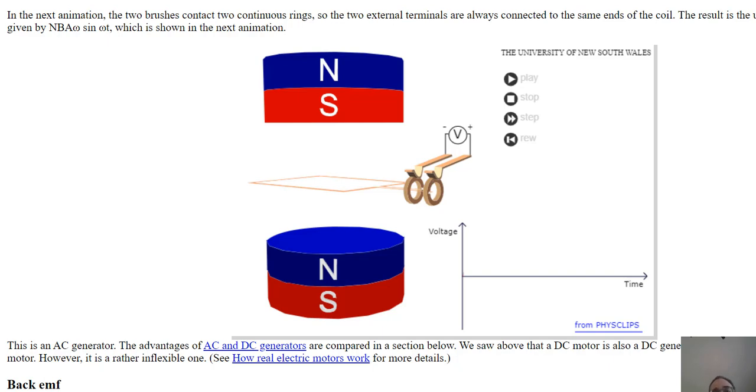Okay. Now, nuclear power, while it may sound really different, is actually almost identical. The only difference is what heats up the water. So in a nuclear power plant, you have nuclear fission, which is the breaking down of large elements into smaller ones. When you do that, you lose a little bit of mass, which turns into energy, heat. And that heat heats up the water, which then boils and turns into high-pressure steam that goes to your turbine again. So the back half of a coal-fired power plant and a nuclear power plant look identical.